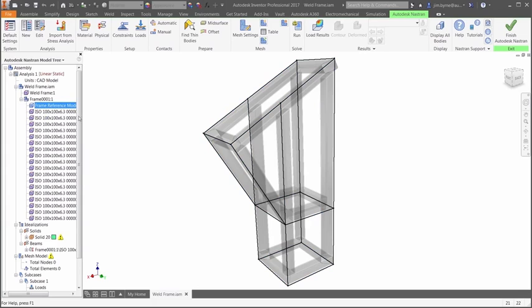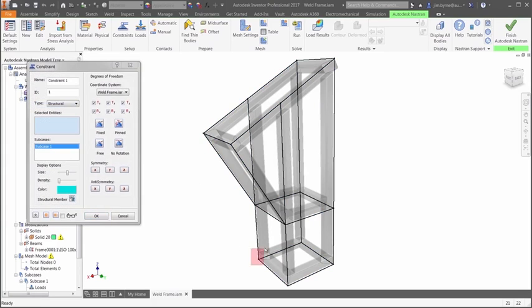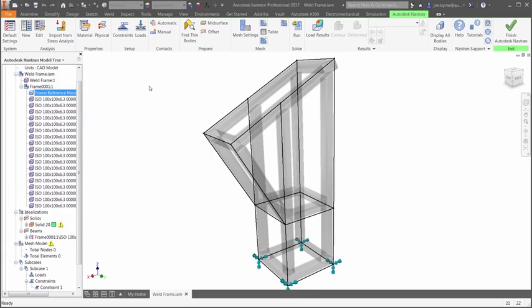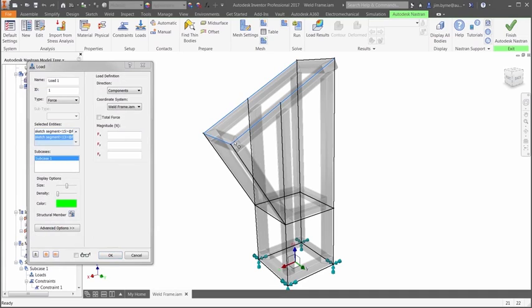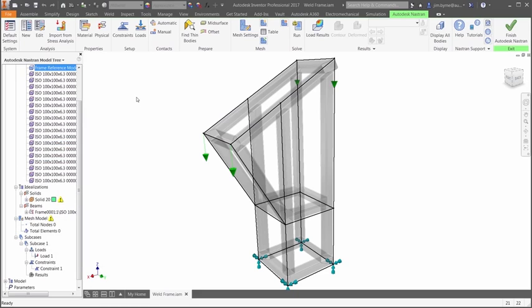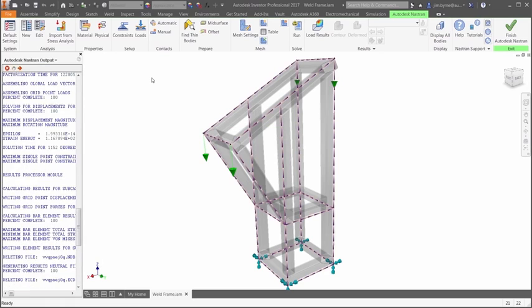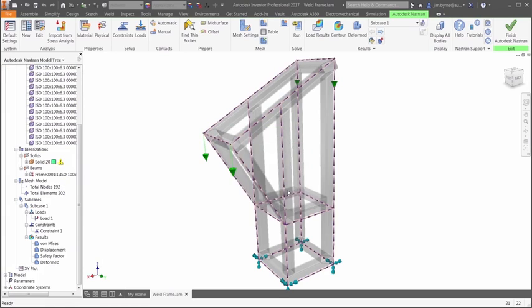Then describe the behavior of the design using boundary conditions. How is the frame held down? And where is the load? In this case, we will simulate the static load or weight of the robot arm which is fastened at the top of the weldment. The mesh will then apply the cross-sectional properties of the steel tubes and run the analysis, which happens almost instantaneously when using line elements.